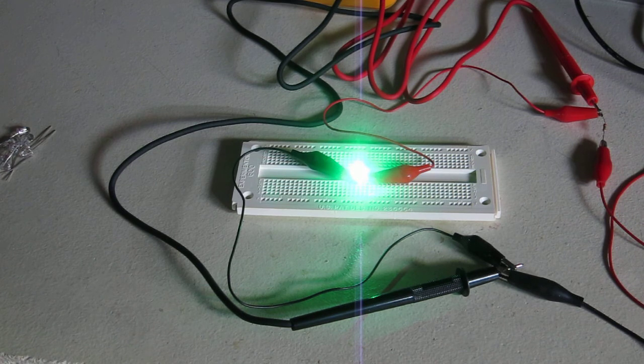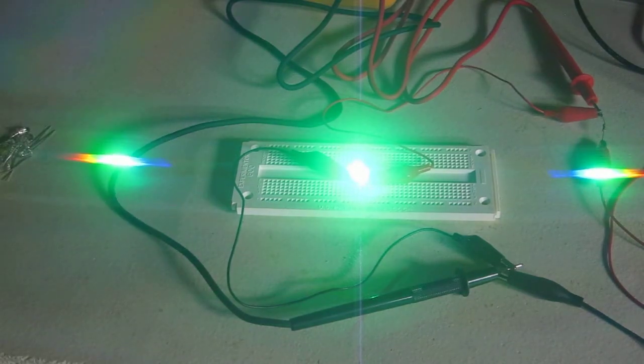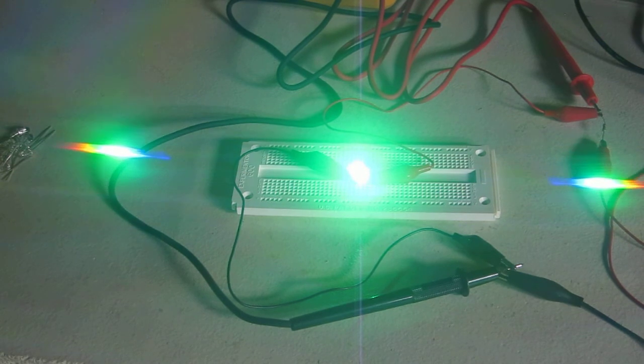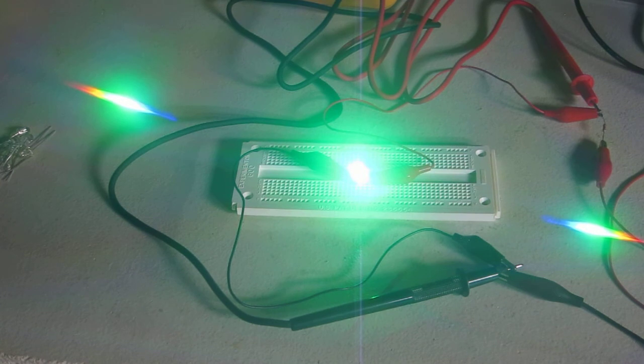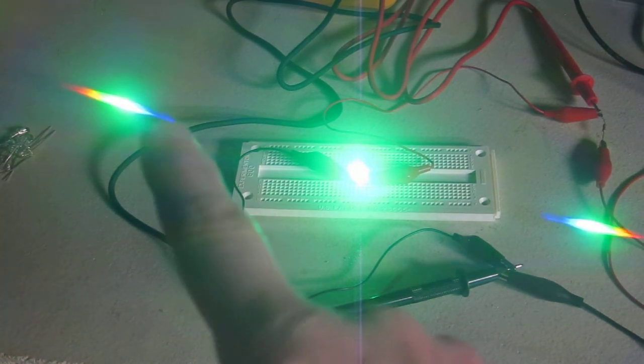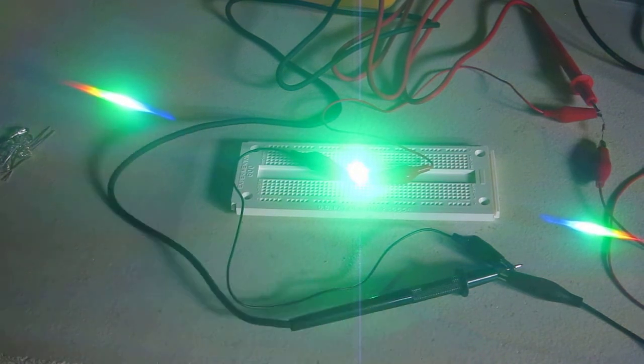When observing the LED, we see the characteristic output. In this case, it's colored green. However, when we use a diffraction grating in front of the camera, something else becomes evident. Notice how our green LED does put out an awful lot of green radiation. However, at the same time, the radiation extends to the blue. You can see the blue streak over here, and into the red and orange areas as well.